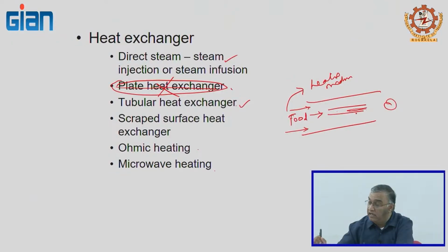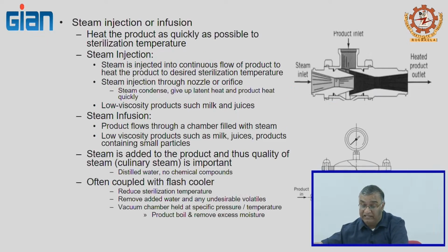For example, when you process protein products like maybe starches and so on, when you are heating them, the material can deposit and form what they call biofilm or something along those lines, and they can reduce the heat transfer efficiency. So, to facilitate removing some of those deposits and also to facilitate mixing, you normally use this rotating mechanism. We will talk about ohmic heating and microwave heating in the next 2 lectures.